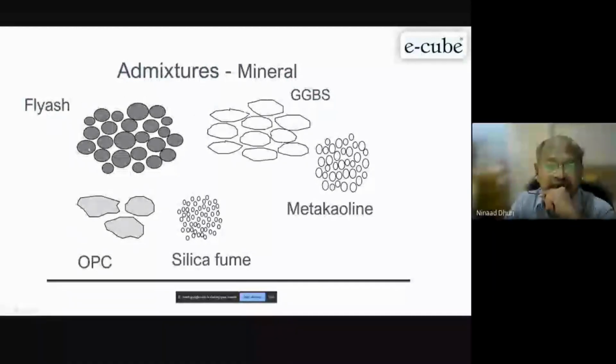That is the major advantage of the fly ash shape. The other material is similar, but very, very fine, so water demand is high. Here it is not that fine, since it is 45 micron to maybe 20 or 10 micron, so you will not get much water demand, and you get a very cohesive mix.